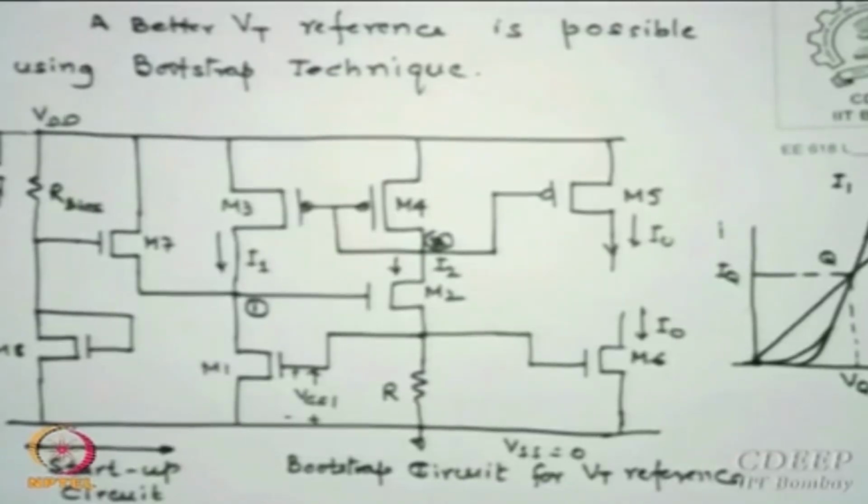So this is the feature of why it is called bootstrap, can you think? I am pulling this voltage up, like pulling oneself up by the bootstraps. Whenever I need, I am supplying a VDD, but I need two VDD. So what do I do? I must hold an earlier VDD on a capacitor, and the lower transistor should switch off, then it becomes 2 VDD. So bootstrap can push voltages like a doubler to more than VDD. And where do you need more than VDD? You need it for short-time transients, which we will do some other time.